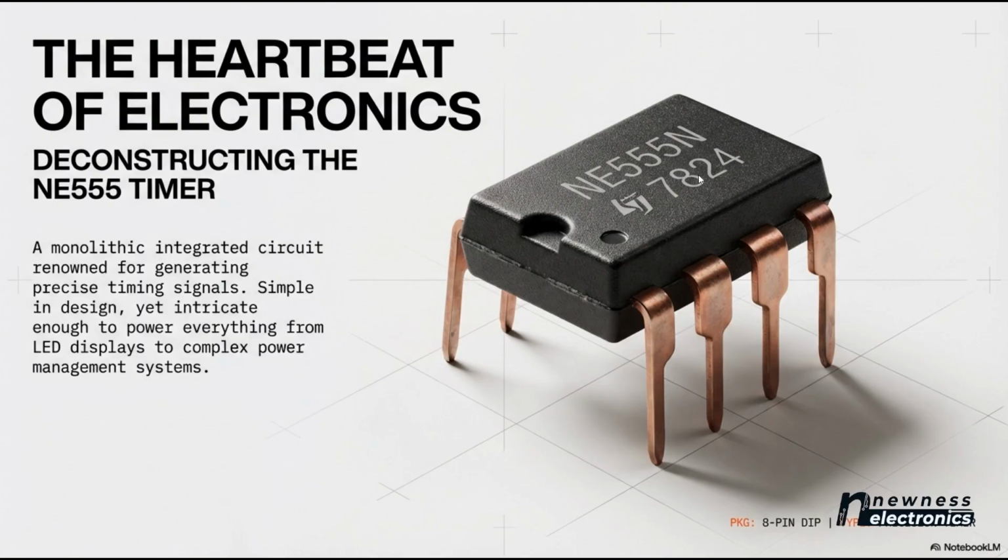Alright, so for this IC, this package is called double inline package, DIL. Double inline means you will see some pins on this side and some pins on the other side. If you count the number of pins on any 555, it's 1, 2, 3, 4, and 4 pins here also, 5, 6, 7, 8. So you call this one 8-pin DIL, which means we have 4 on this side and 4 on the other side.